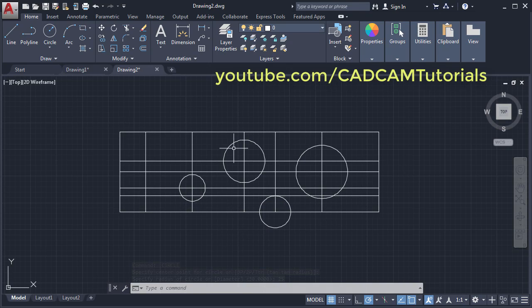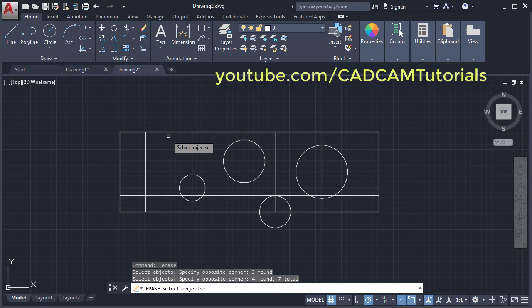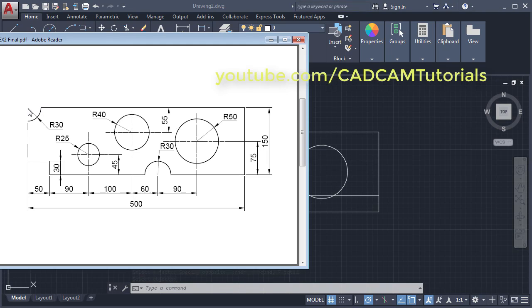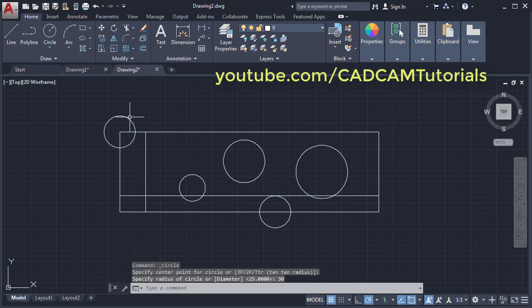Then remove the unwanted lines. For that, click on erase and select these 3 lines and these 4 lines and press enter. Then we need one more circle at this point of 30 radius. Click on circle, give the center point, give the radius of 30, enter.